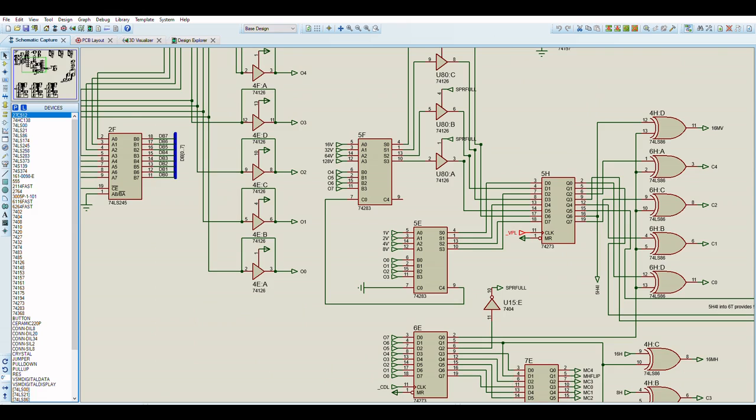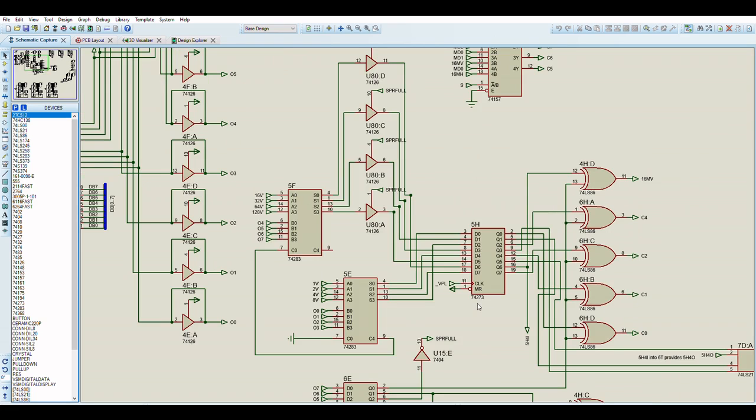So the format for the sprite data is that byte 0 is the tile code, byte 1 is the palette index plus the flips and the full screen sprite, and then byte 2 is the sprite's X position and byte 3 is the sprite's Y position. So as it's timing the read for the sprite Y position, this VPL is triggered. So basically what it does is that it clocks the output of an 8-bit add.